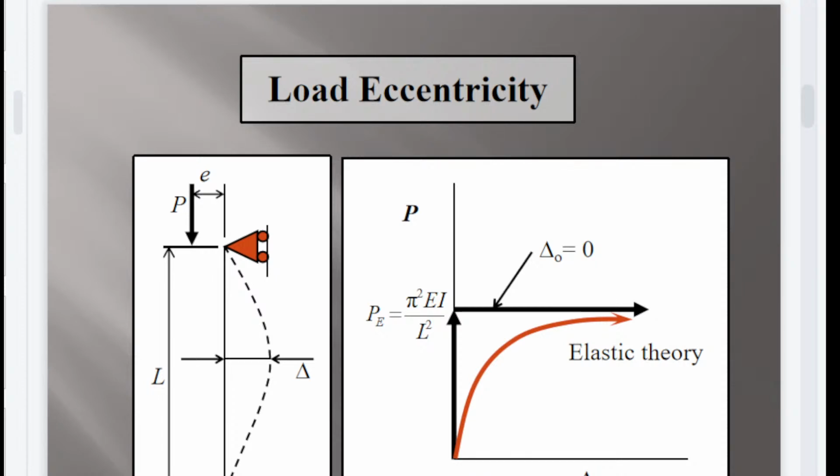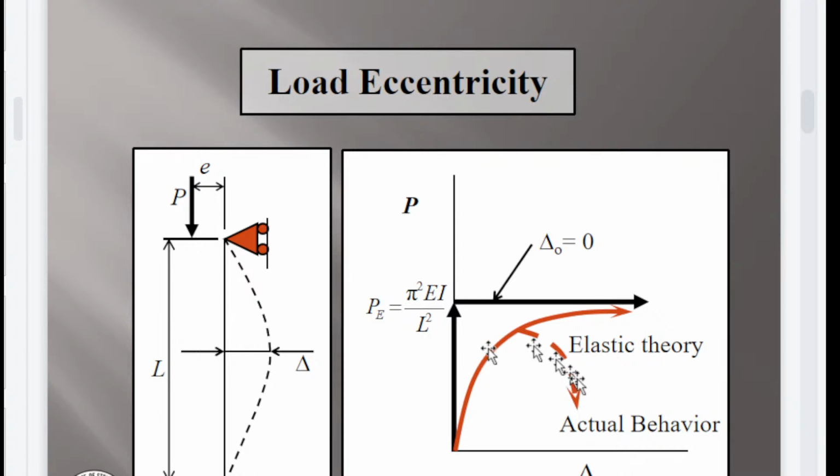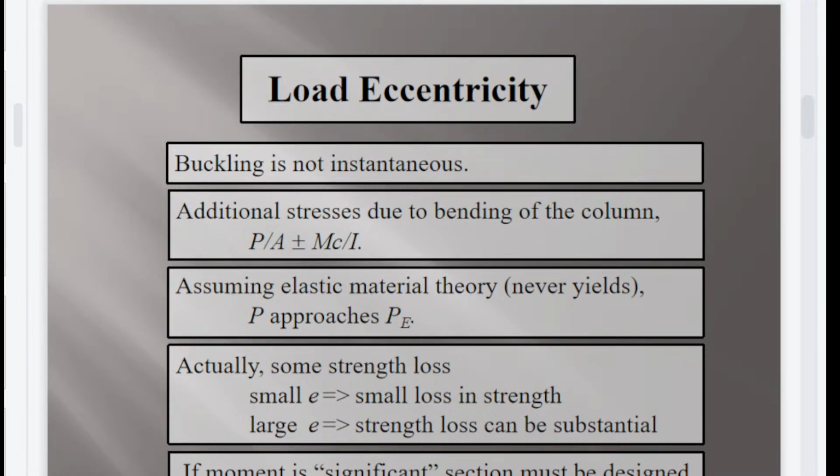So next is about load eccentricity. If our element experiences this, as you can see, we have the same discussion, so we just repeated. So the load eccentricity assumption: if a moment is significant, the section must be designed as a member subjected to combined load.